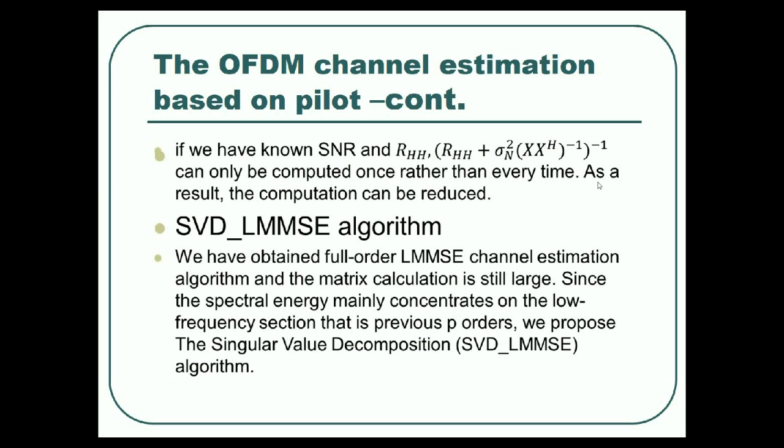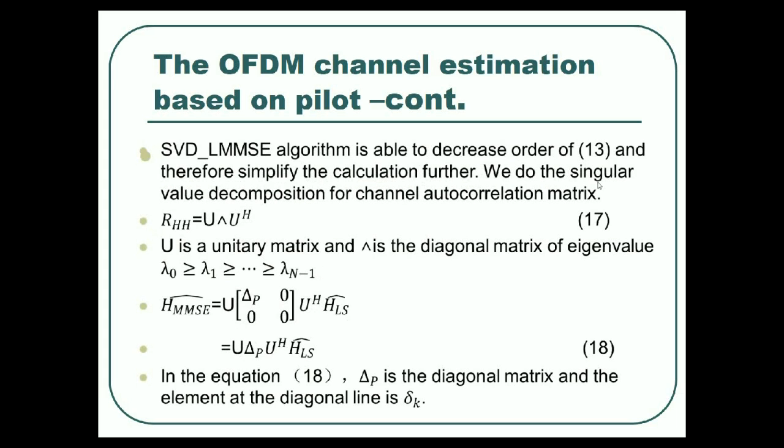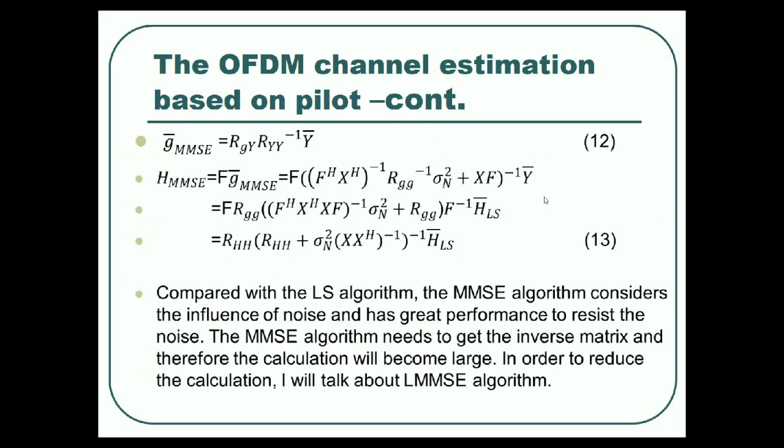So we introduce the SVD LMMSE algorithm. The SVD is the singular value decomposition. Since the spectral energy concentrates on the low frequency section, that is the previous p orders, we just use the p orders and ignore the other orders. This algorithm is able to decrease the order of equation 13. Okay, I will show that. Okay, this formula.